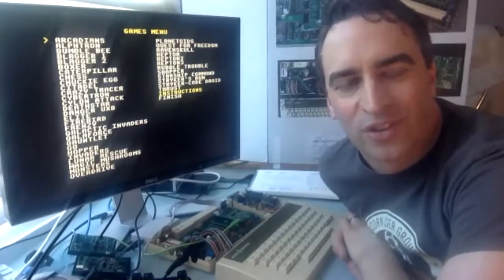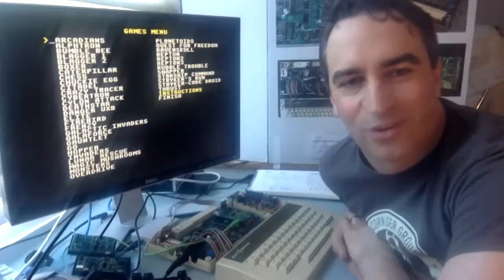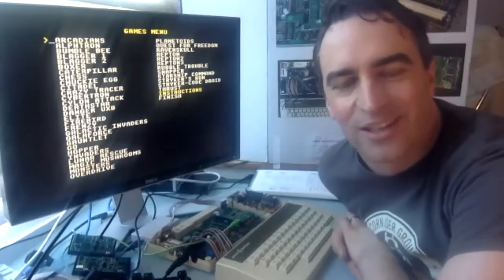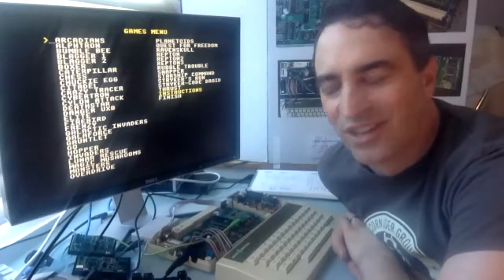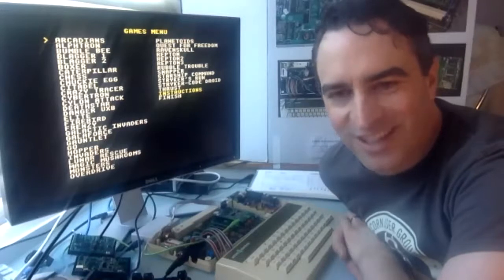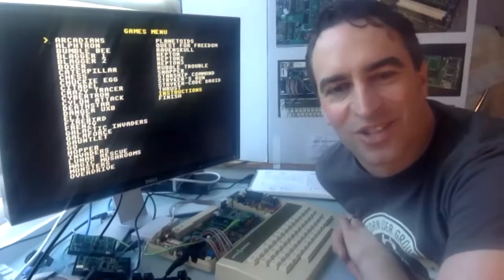Of course, hardware doesn't work that way. Hardware is flip-flops. Stuff changes when the clock happens or sometime around it. But in simulation, you can do whatever you like. And so I've seen the flash chip and the SDRAM chip implemented like that in the test only.